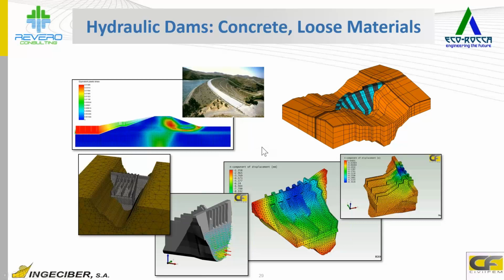Another area of usage of CivilFEM would be in calculating hydraulic dams, which could be of concrete or loose materials, and as mentioned previously, we can have a seepage analysis or a structural analysis or an integrated analysis of the dam.